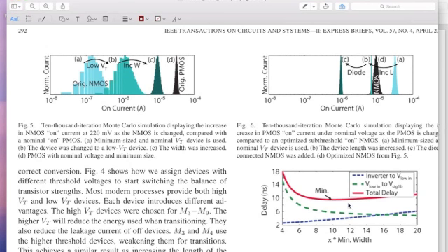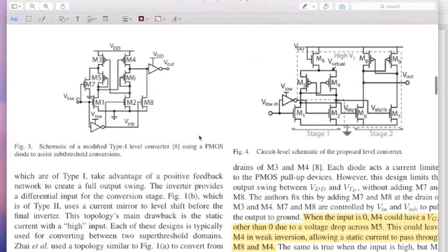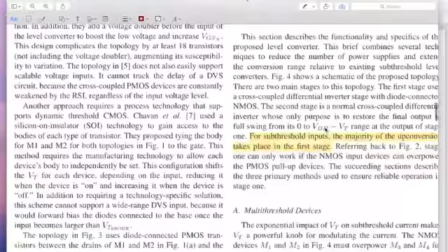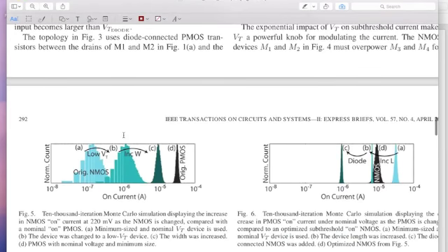By simulation they try different sizes, and when you increase the size, what happens is that the delay to drive the signal to the first stage increases, because there are some other inverters which are driving this. Those inverters are kept fixed, but this first stage is being driven by some circuitry out here. This circuitry size is kept fixed, but as you increase the size of these, this delay increases, but the delay of this decreases. So then you find the sum of the delay where it comes to be minimum, and they plot this graph, and from there they pick a certain width which helps them to improve.